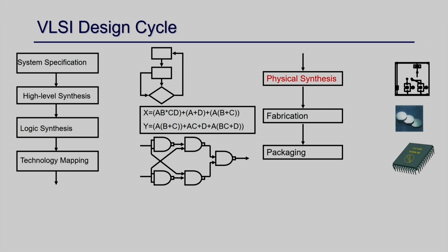So, if you think about what we have after the technology mapping step, you have a gate level circuit, which is a huge circuit, represented by the cell libraries. If it is FPGA, then it might be LUTs, RAMs, DSPs, or if it is ASIC, then it is the library elements like NAND gate, NOR gate, basic flip flops, RAMs and all, right. So, this is the representation.